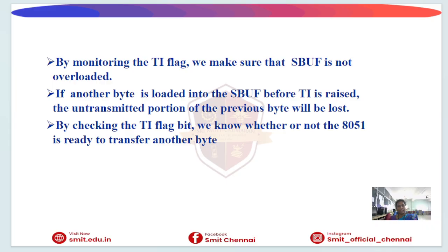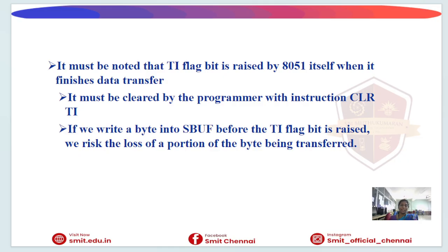If the previous transmission is not completed, then we lose the whole content, the whole characters in the SBUF register, or they get corrupted in the SBUF register. Next one is clearing the TI flag.